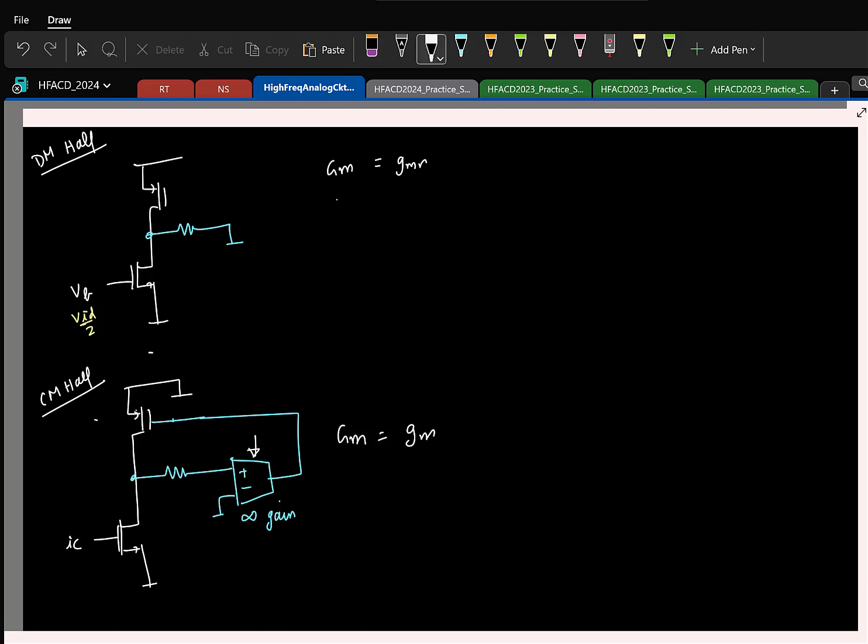The R out is simple. What is the R out? The parallel resistance of the NMOS and PMOS, parallel to the common mode resistor used. Let us say this is RCM. So here let's find the same. Here what is the output resistance? Let's say looking down, what is the resistance here? So at least that should be clear. Looking down, it is the R0 of the NMOS. So what is the thing looking up, do you think? 1 by?